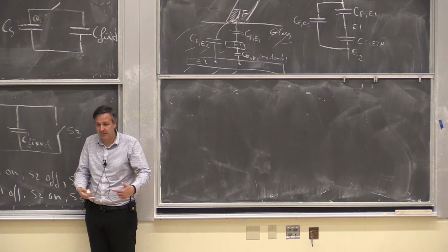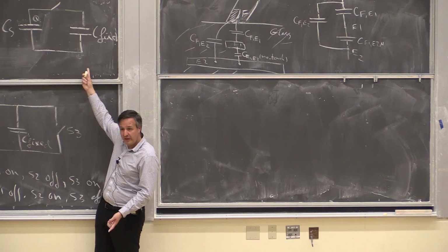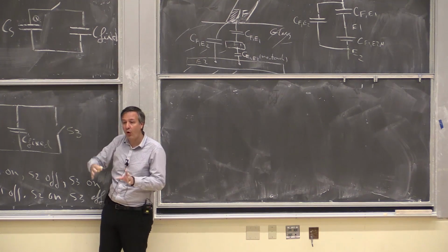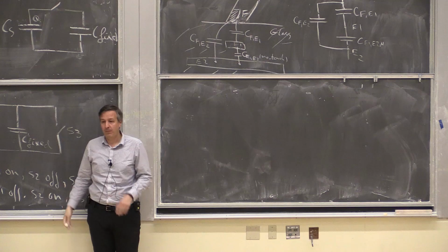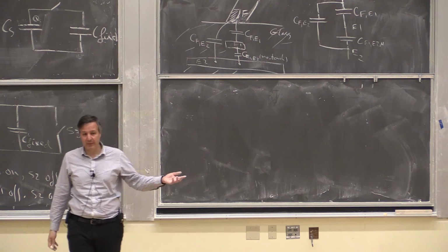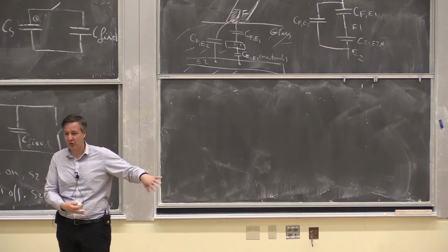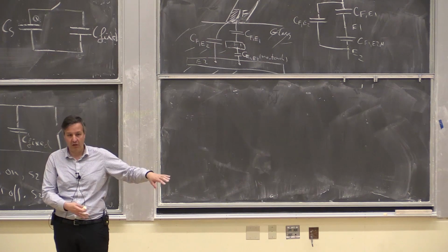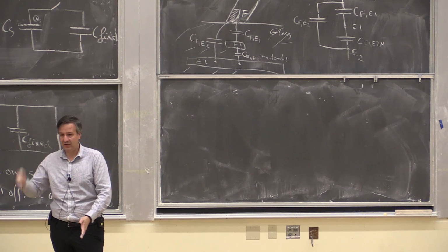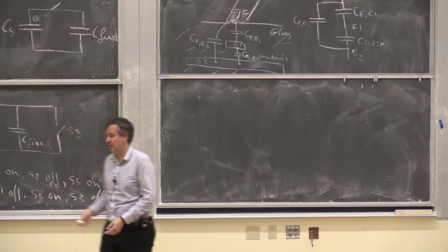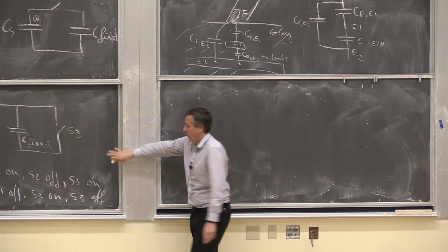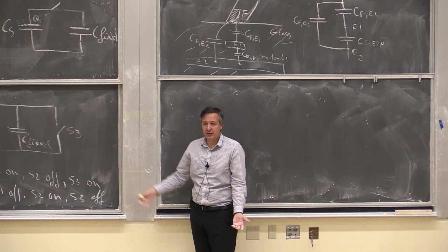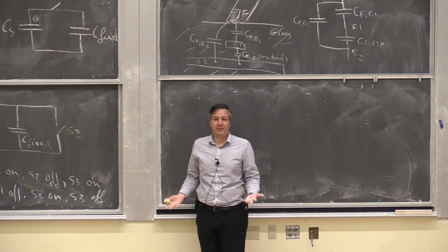That prepares it for phase 2 when it needs to be shared, so that there's always 0 charge on that other capacitor. Whatever happened before, this removes the history. Whatever was before, you don't care. Now you want to do the measurement. So it's a clean capacitor, it's empty.